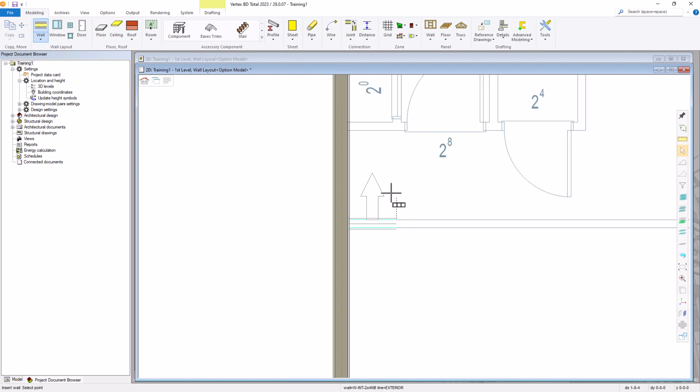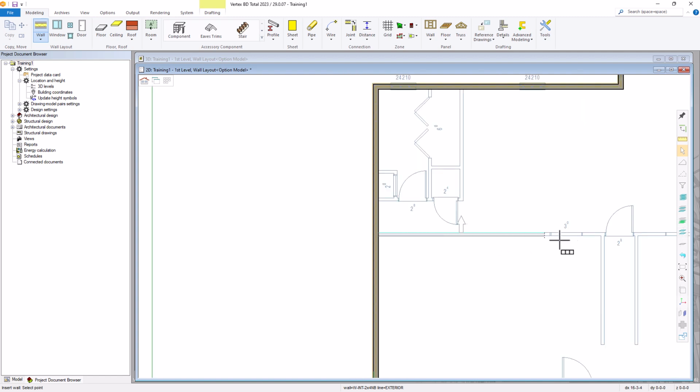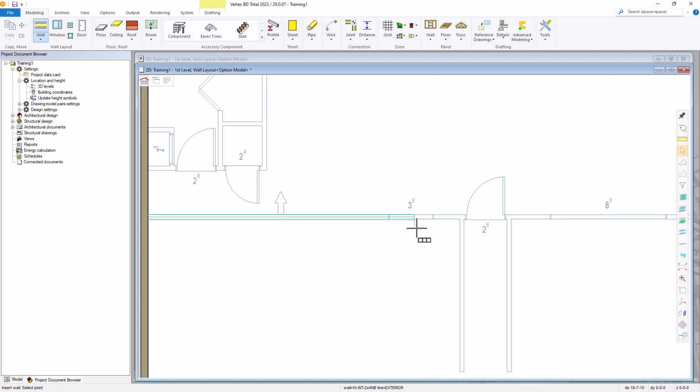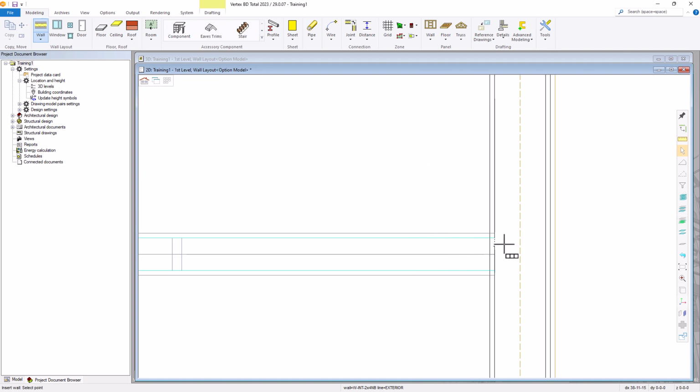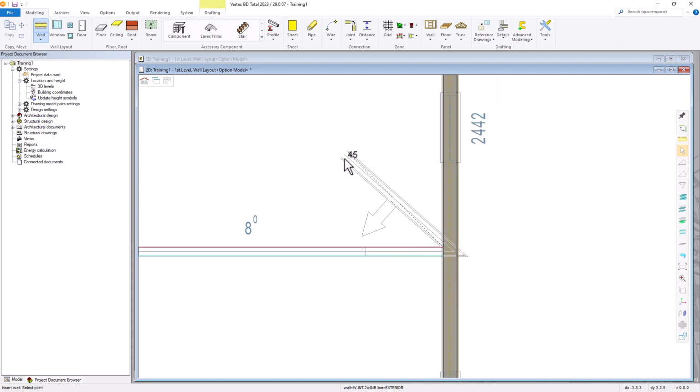Now it's pointing upward for the exterior side. It's an interior wall. Both sides are the same. They have 1/2-inch drywall on each side. So the exterior side isn't as important, and that's not a big concern when it comes to interior walls. So I'm just going to go ahead, and it's locked in the horizontal. Go all the way to the other side and just click an intersection point on the opposite side. Now we're done adding walls.